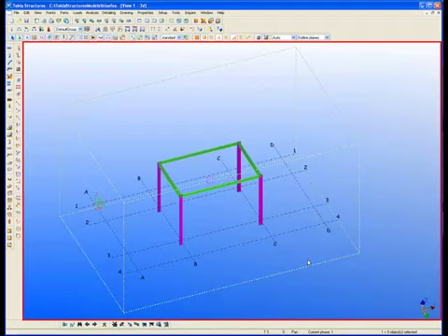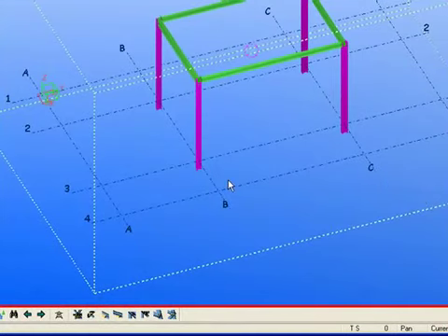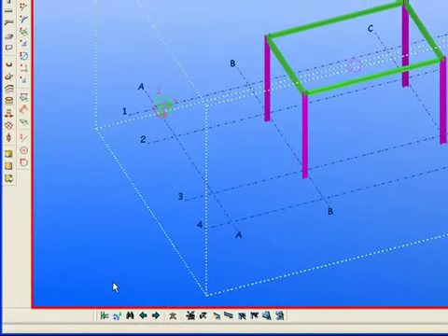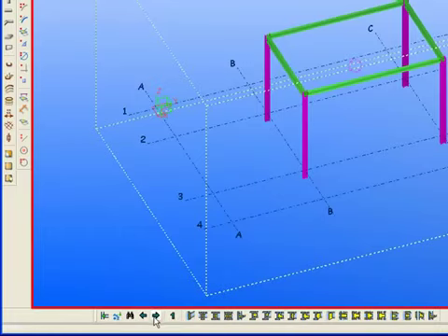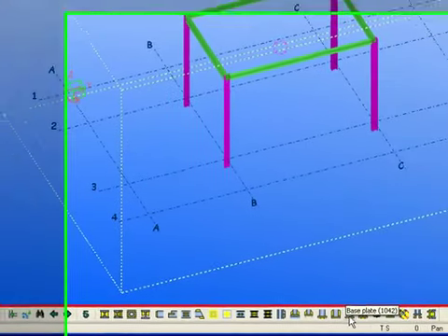Okay, let's apply a baseplate macro to our column. By using the component connection, now just flip to page 5. That's where we will find our baseplate macro. Just click on the arrow here. Go to page 5, and I will be using baseplate 1042.